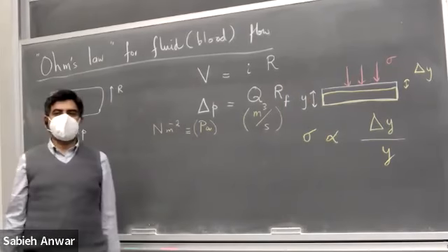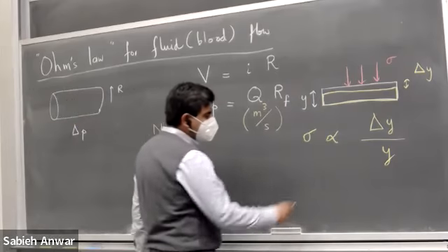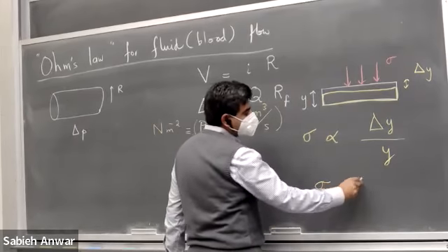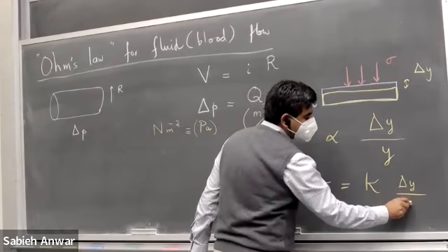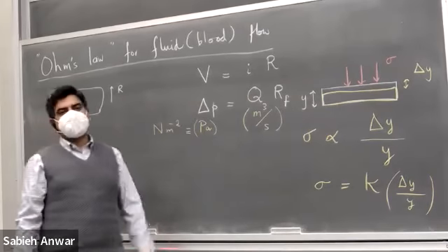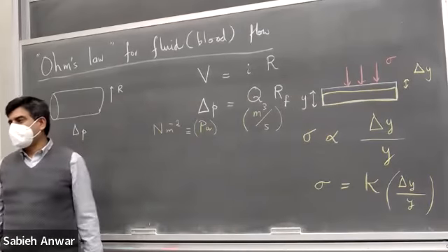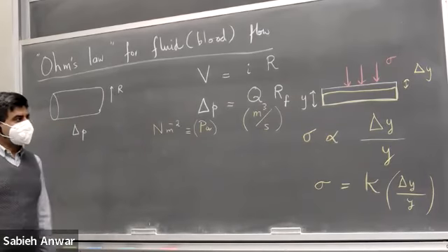This is called Hooke's law. The stress and the strain are directly proportional, and you can insert some proportionality constant, let's call it the Hooke's constant. So this is true for an elastic solid, the simplest solid that you can think of. You apply a stress to it, and a strain develops in this object.